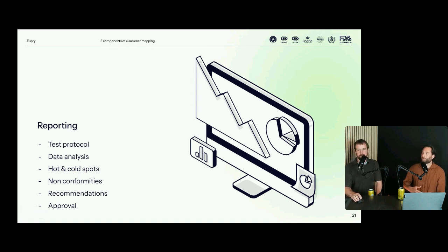A fully loaded warehouse might deviate the airstreams that your HVAC system is blowing and create different hot and cold spots. And for warehouses that have a high volume and always different fluctuations in the goods that are stored, I do see a 0, 50, and 100% loaded test being worthwhile.